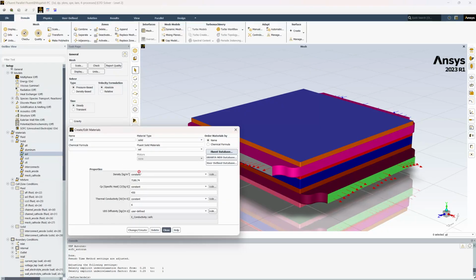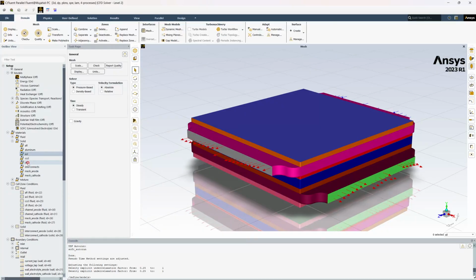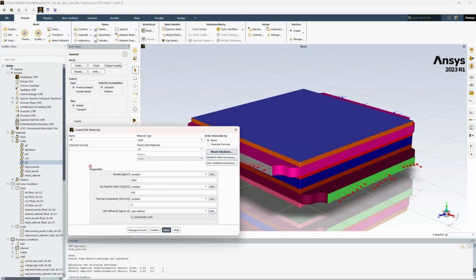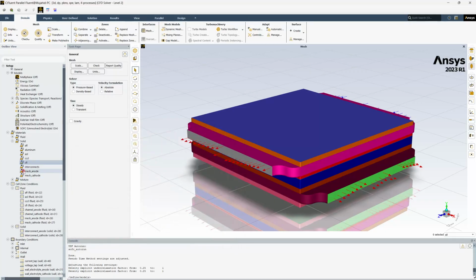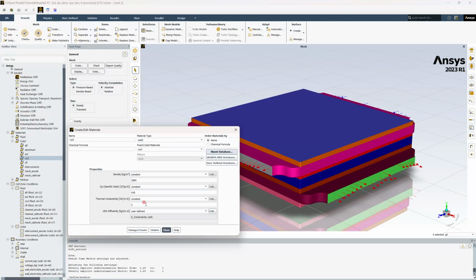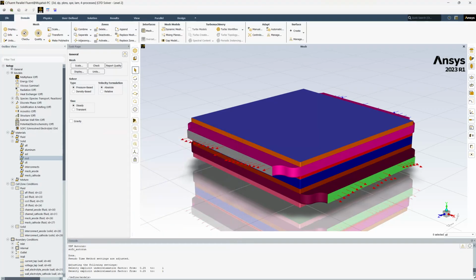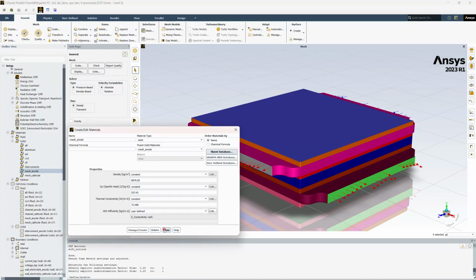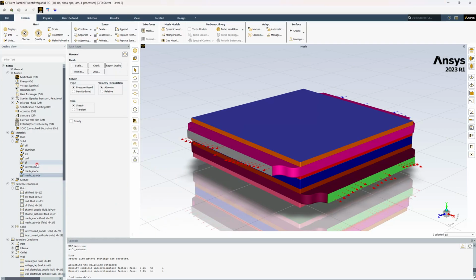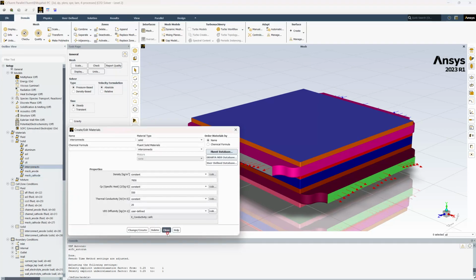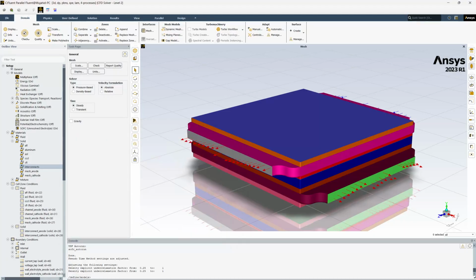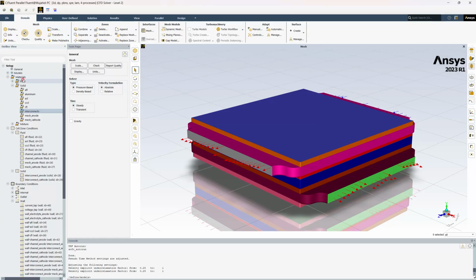AFL, and then we have ASL, CFL, yes, CCCL, yes, and then we have the meshes, mesh anode, mesh cathode, and the interconnects. Yes. Now after defining the materials, we need to apply them to the actual cell zones. So we have finished defining the materials.